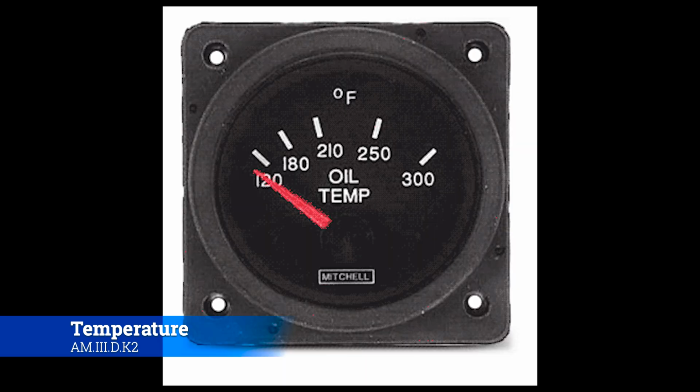Okay, the next temperature gauge we're going to look at is going to be oil temperature. So oil, obviously, if it's too cold, it's going to want to be super duper viscous, and it's not going to have the same cooling or cleaning effects that we want it to have inside of the engine. So obviously that's bad. It won't necessarily lead to the engine running rough per se. However, there are examples of people operating in the Arctic where the oil basically has water in it and then it just freezes solid and it won't run at all. So that could be a problem.